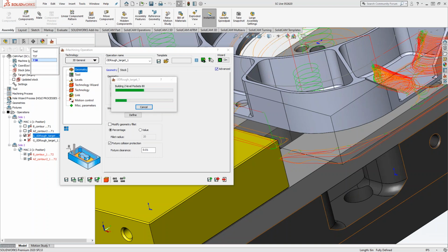what I'm actually doing is I'm recalculating the use of the second tool with its own working area, because I noticed, if you look on screen right now, the toolpath we're looking at is using tool 57. That's my 1-inch diameter tool, and you can see that in this case right here, it's avoiding the fixture. But the second tool that we're using actually has enough room between the fixture and the part to actually go and remove a little bit of material there. And obviously I don't want it to do that because that's where we're actually holding the part.